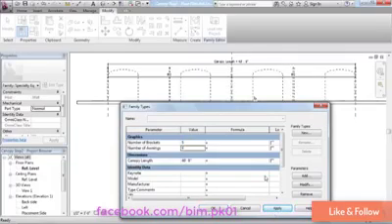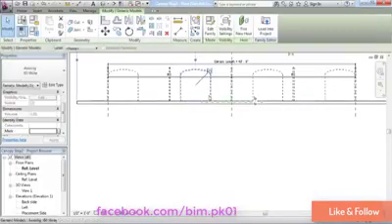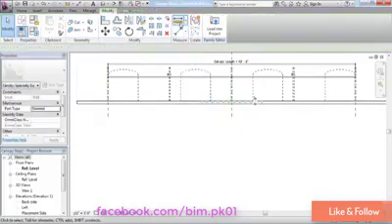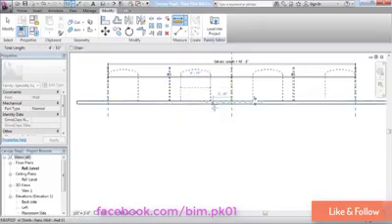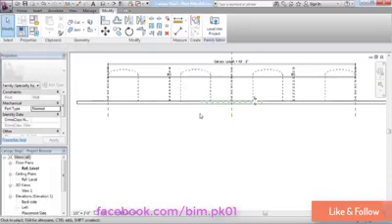Of course, I've chosen some rather random numbers there, and you can see that nothing really quite matches up except the 2 at the ends. Well, if we look at the overall length here, 40 feet, and we select this guy, you notice the name of the awning within that group is called 60 wide. And if you really want to verify that, I could do a measurement and measure it, and it's 4'10" plus the inch gap on either side. So the overall width of this awning is actually 5 feet.